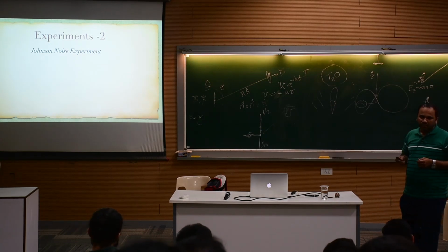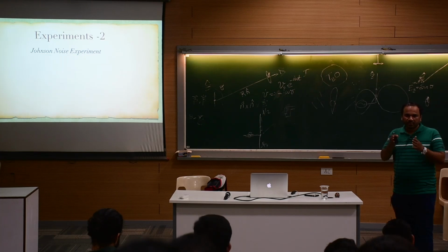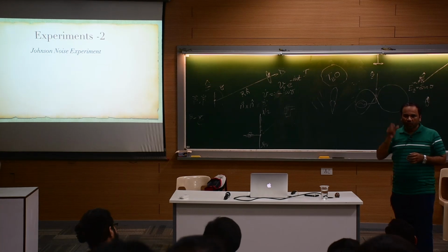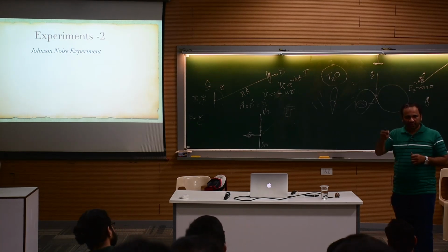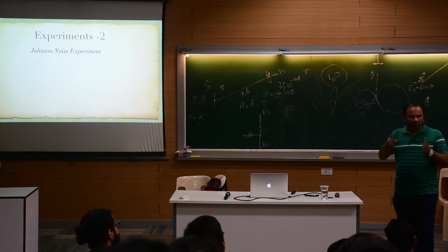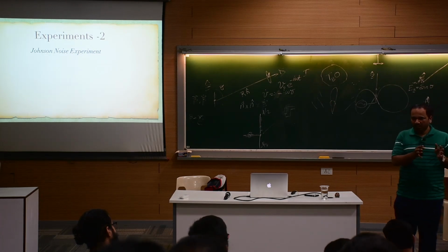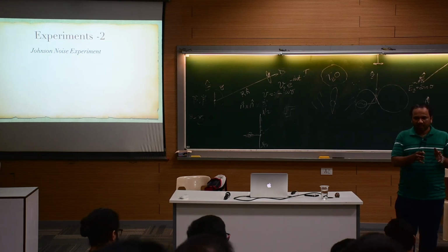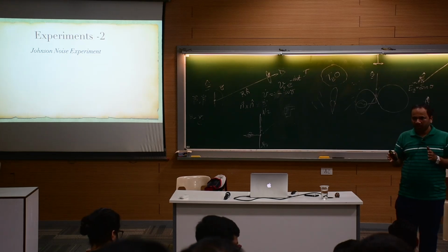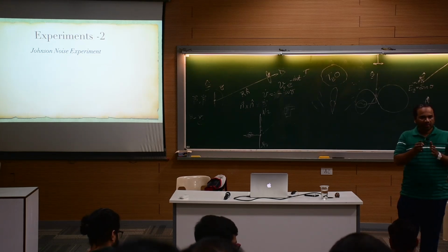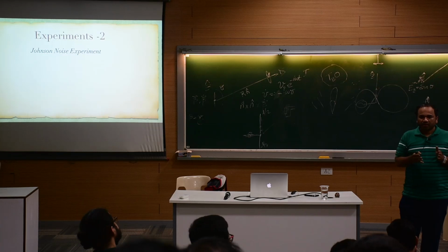It is also called Johnson-Nyquist noise because Johnson was the first person at Bell Lab who studied this noise, and Nyquist derived the whole derivation and came up with a systematic investigation of it. He said it depends not only on a few parameters of an electronic system, like resistance. Any electronic equipment consists of passive elements, right? It is made up of resistance, capacitance, and inductors, and all of them have resistivity.